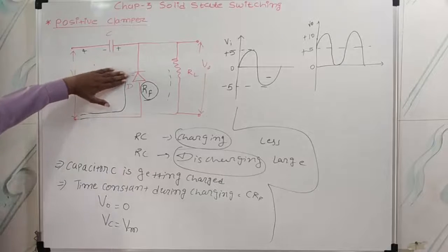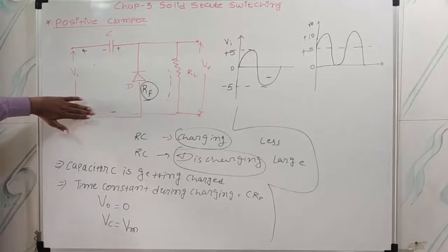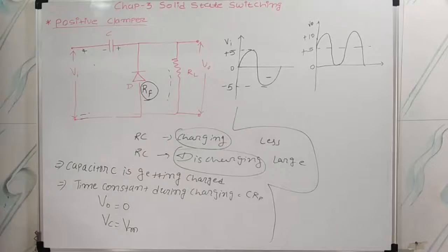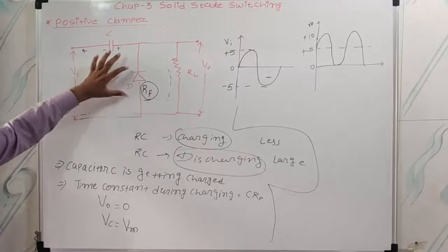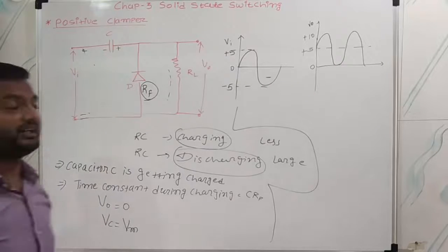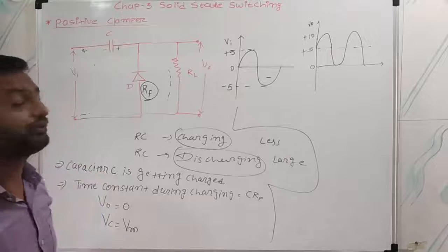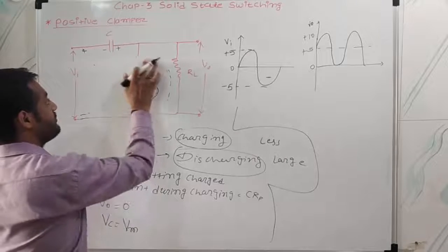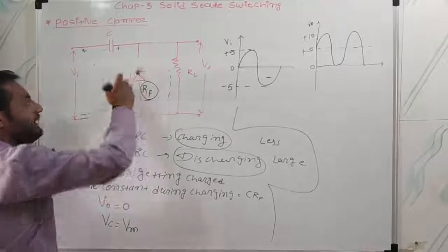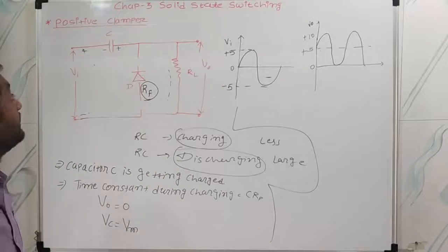Now I'm just going to remove this arrow, right? Okay. Now this one is positive, this one is negative, this diode is in reverse bias direction, and because of that it will work as an open circuit condition like this. There will be no branch in between them.